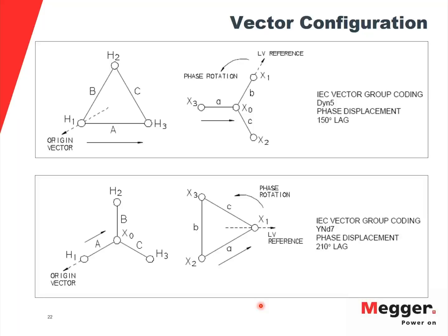And the other nice thing is this is actually one of the tests we do to verify that your LTC is working properly. We're making sure that whenever you're transitioning from one tap to the next, you're making a connection to that next tap before you break the connection from the previous tap.